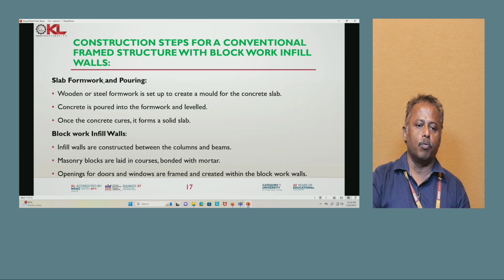Next, slab formwork and pouring. Wooden or steel formwork is set up to create the mold for the concrete slab. The concrete is poured into the formwork and leveled. Once cured, the concrete forms a solid slab.